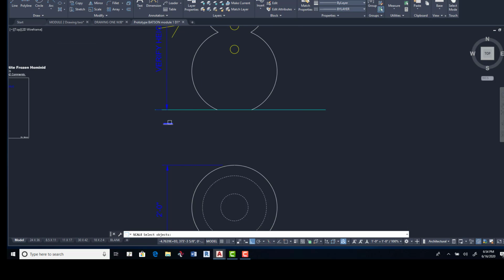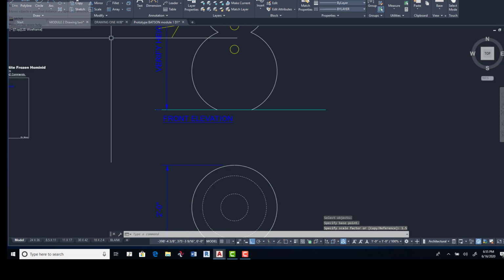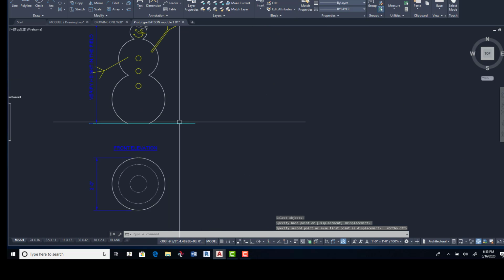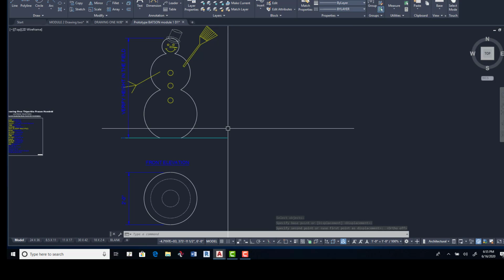Left select, right click on your mouse, and then left select the base point, and then type in something like 3 or 4. I'll type in 5 times, 5, enter. That's pretty good. It can go a little bit more. So let's right click, left select, right click, left select. Let's type in 1.5. There you go. So let's go to move it, left select, right click, left select, and take your ortho off so we can eyeball it right there. That's good.